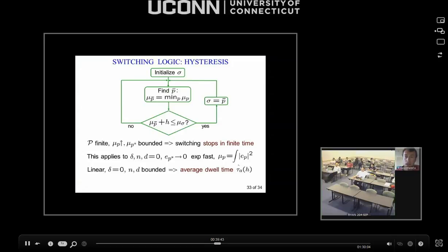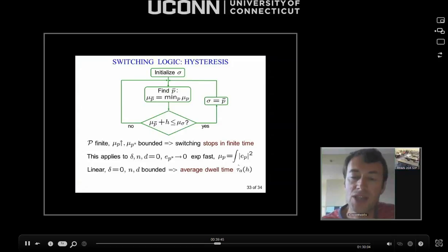As a first approximation, you can think of having one candidate controller for each possible value of the parameter, and in that case, the cardinality of the uncertainty set and the cardinality of the controller family would be the same.